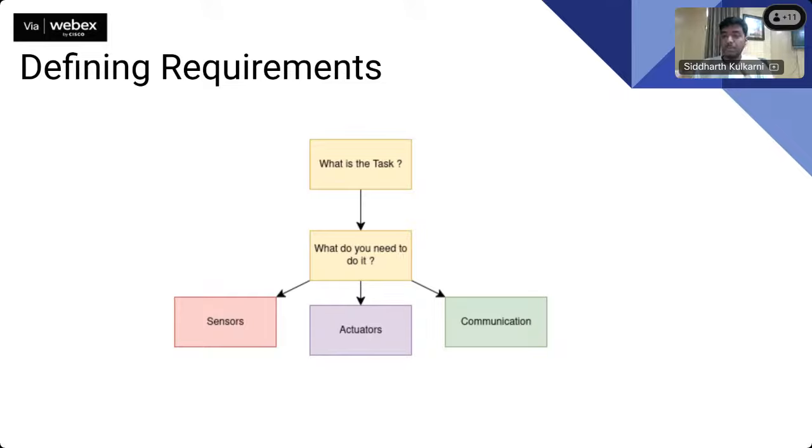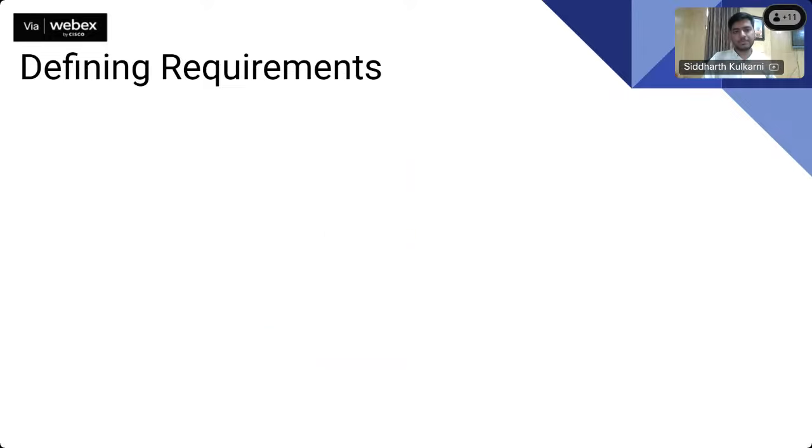Now again, there are multiple categories within soil moisture sensors themselves. There can be a capacitive soil moisture sensor, a digital soil moisture sensor, an analog soil moisture sensor, and all these sensors have different working principles. So based on the phenomenon that you are trying to decipher using this sensor, you need to choose your sensor wisely. What I've tried to do is narrow it down from big different use cases and different sensors to a more magnified version of it. That is, there can be different types of soil moisture sensor, and each type might be good for some other activity. So you need to be sure about that.